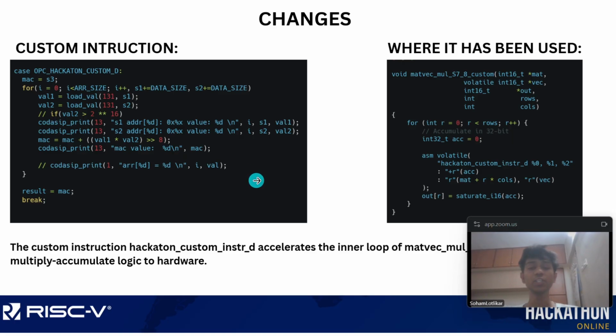While reading the hints, especially the part about Googling SIMD, we got inspired to think in terms of data parallelism, which shaped the design of instruction D, as well as instruction F. Although we weren't entirely sure if it was parallel at the hardware level, it helped us save a significant number of cycles in practice. This instruction specifically handles multiply and accumulate operations, referencing values of a matrix and a vector. It processes by unpacking 4 units at a time, which mimics SIMD-style behavior, making it more efficient than handling each element sequentially.